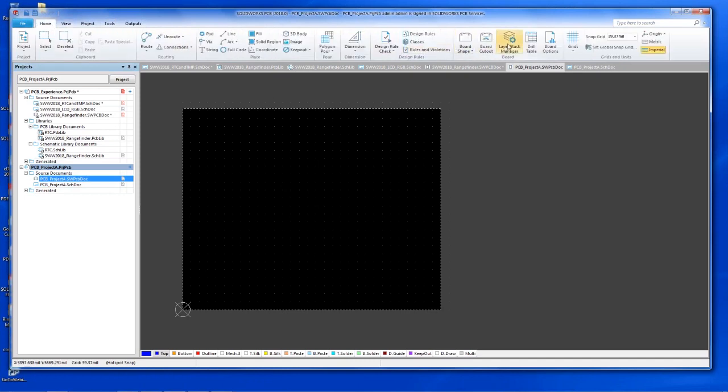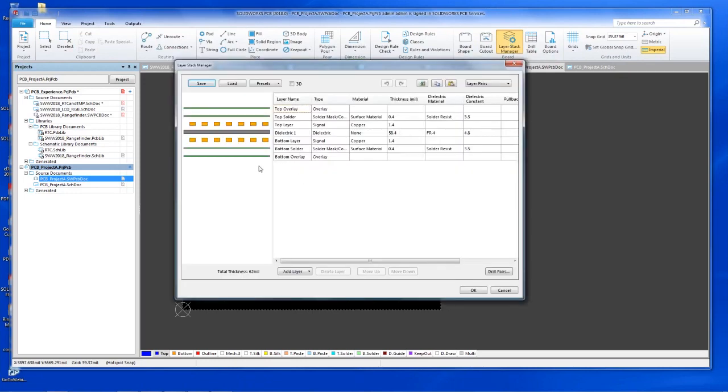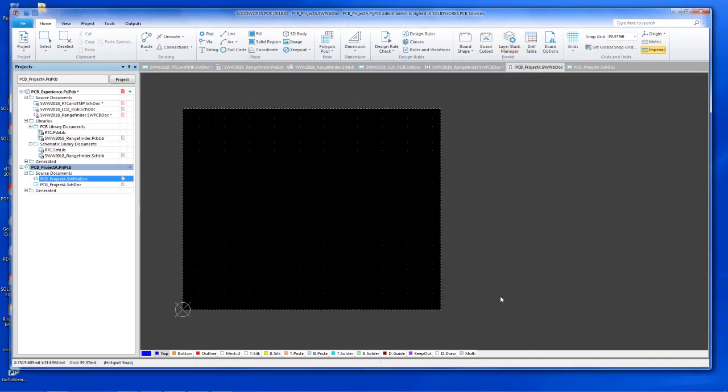A feature of the tool is when you look at your circuit board layer stack up, which defines your layers, your dielectric thicknesses, you get an overall thickness. Okay, this board happens to be 062 or 62 mils. That's a pretty common circuit board thickness, along with 125s. I mean, there's definitely some industry commonality there. SolidWorks reads this thickness and creates the board exactly as you have defined in your layer stack up. So that's an important feature. You'll want to set that up first.